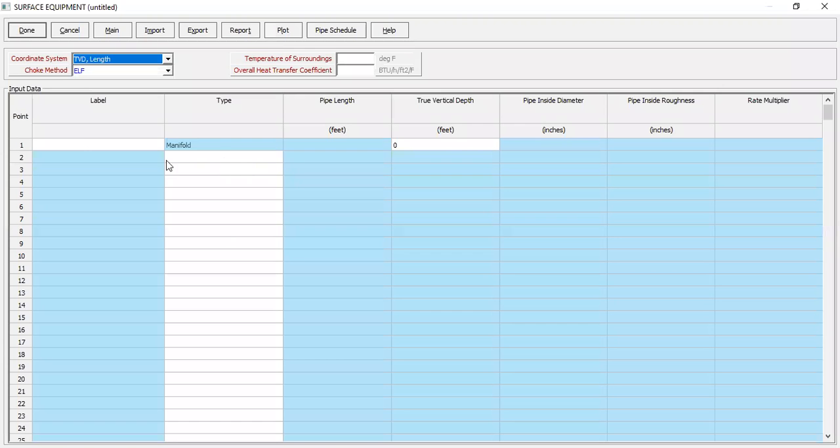Okay, so for the surface equipment, you can follow me. I will maximize coordinate system, TVD and length, choke method, ELF, temperature of the surrounding, 52 degrees Fahrenheit, with overall heat transfer coefficient of 8.5.